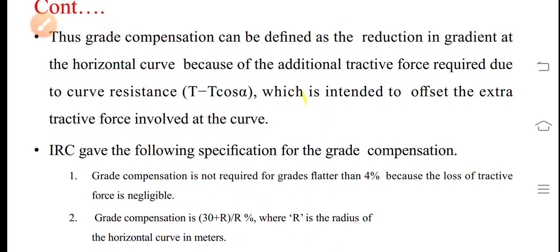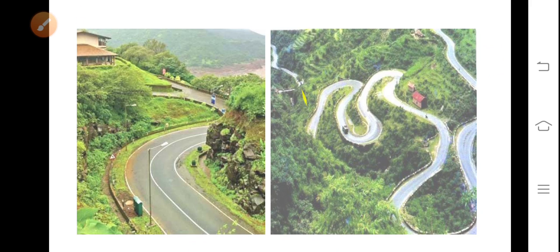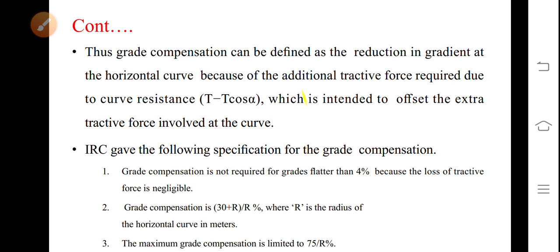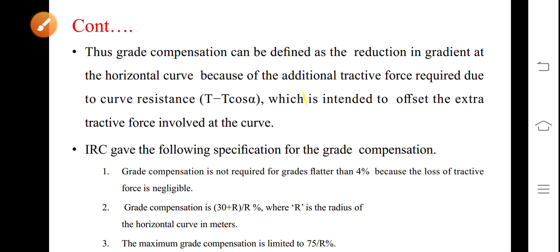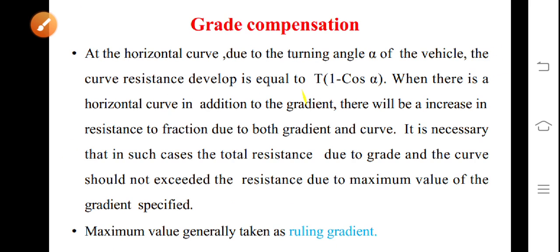Grade compensation is not required for grades flatter than 4%. If the gradient is flatter than 4%, there is no necessity of grade compensation because the loss of tractive force is negligible. There will be loss, but it is very negligible. Hence, grade compensation is not at all required. Grade compensation is